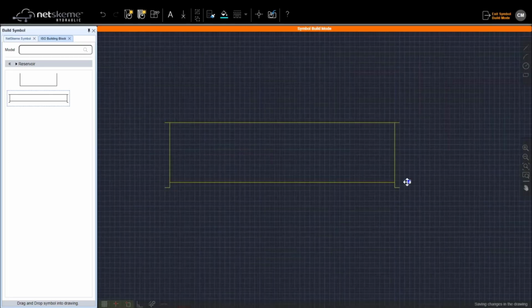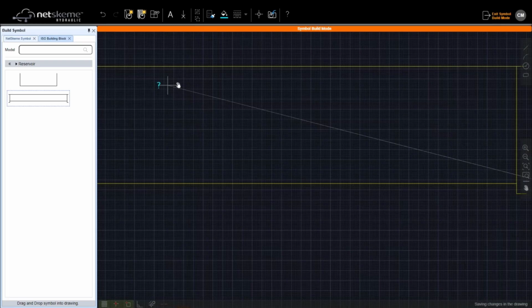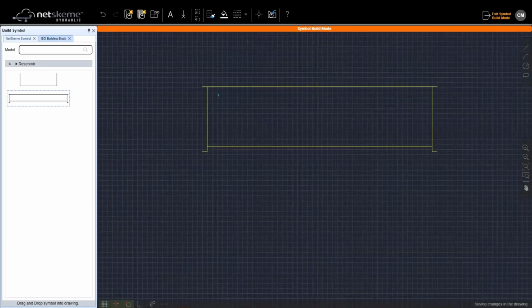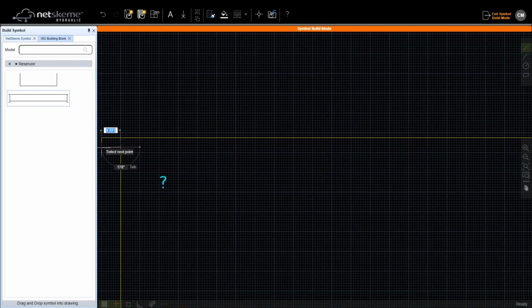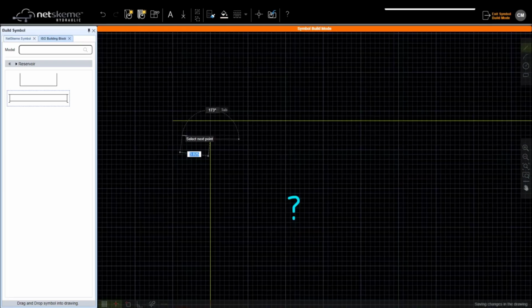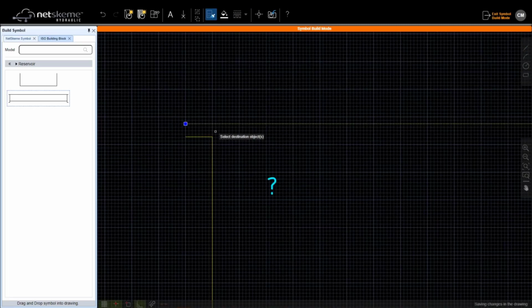And the item ID is represented by this question mark. It is the position of the balloon. And let's say that this is going to be slightly there. And we want another line, F3, F8. You can use the copy attributes to apply the same drawing style to entities in the drawing.